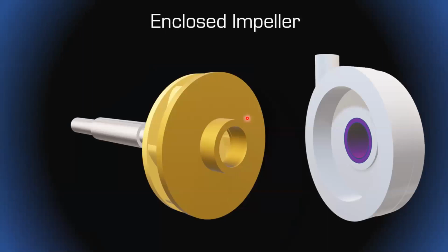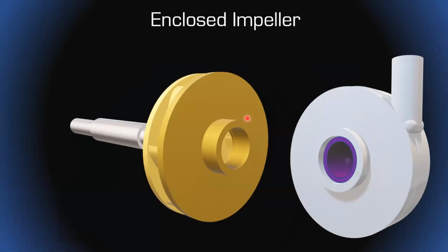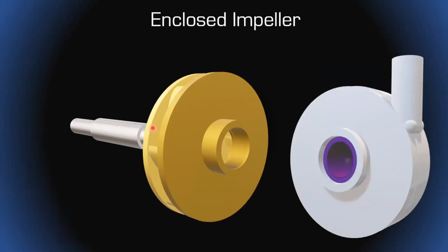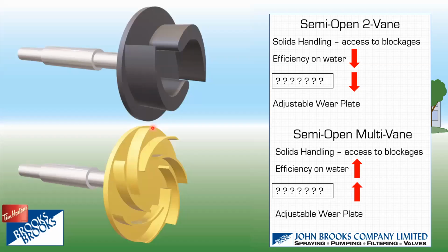And again, this is the difference between a less expensive pump and a more expensive or valuable pump. It all depends what you're pumping. And once we've worn that away, we turn the volute around and we can push that wear ring out. Just to go back one, with very abrasive material we sometimes will also want to put a wear ring around the case as well, because there's going to be some high velocities around here. So there's a few ways that we can keep a pump up and going.